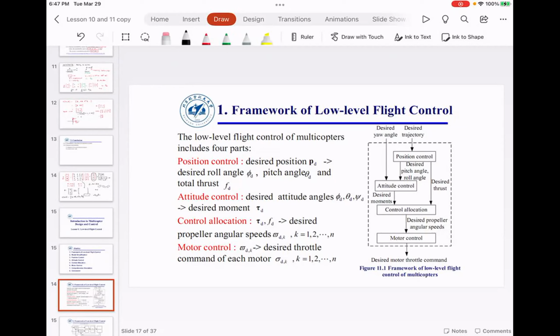So this is how the basic control algorithm is going to look. First, you will use a complementary filter, find out the roll and pitch, and stabilize the roll and pitch. Everyone understood this? That is the first step. Second, you will measure the height using the pressure sensor and the ultrasonic sensor and use that to stabilize altitude.